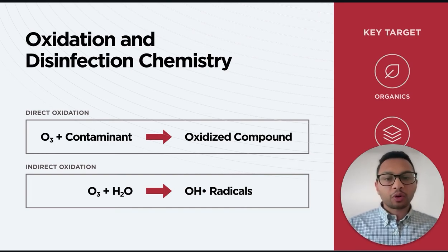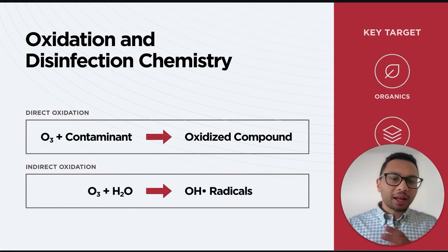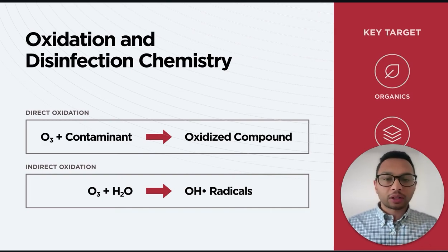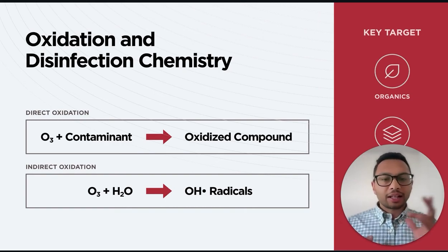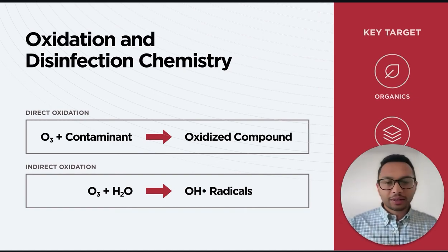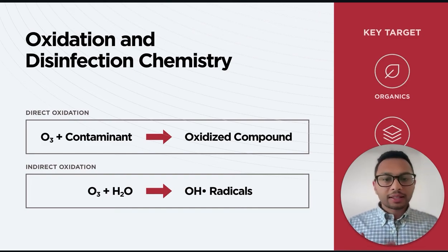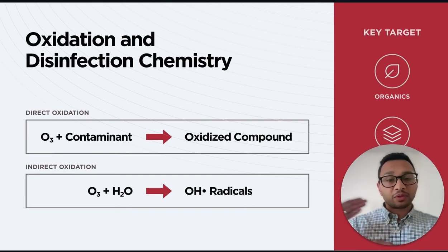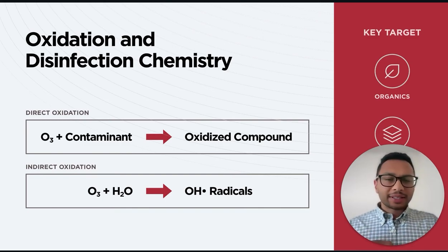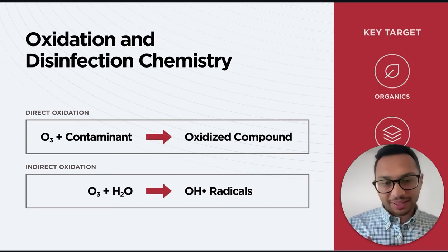They will react with almost any organic molecule they encounter, and this makes it more efficient. This is a process that we call AOP, or advanced oxidation processing. To put this in perspective, the rate at which ozone reacts with phenol is about 1.3 million per molar per second. The same reaction with the hydroxyl radical is 5,000 times faster, 6.6 million per molar per second.